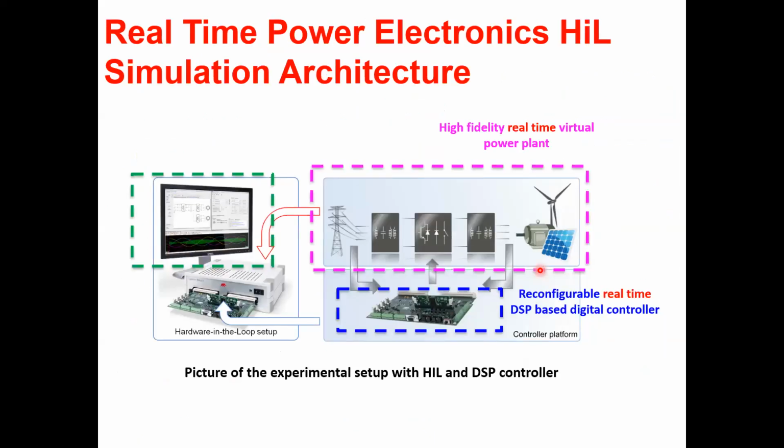So finally, I would want to stop with this, especially for renewable energy and large applications. People are increasingly going with real-time simulation. You can have a digital system with real-time hardware in the loop circuit with the same controller hardware, but in this case, this is actually a practical, actual inverter system. Here it is actually modeled on a computer. So you'll be able to check the performance. And if any anomaly is detected from the actual system with respect to its operation in the computer, people are trying to use that to predict the failure. And such research is also going on.